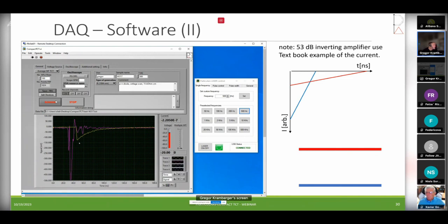Again, you will be able to see basically the textbook example of how the induced current looks like in a silicon diode. So at 0, at -10, it's not depleted, you get this long tail, yeah? And then at 20, you still may not see that it's fully depleted, but at 30, you will already see that this ends here, and you have this linear part here and the other linear part here. So you see this nice textbook example of how the current should look like for the infrared. It's really like a textbook.